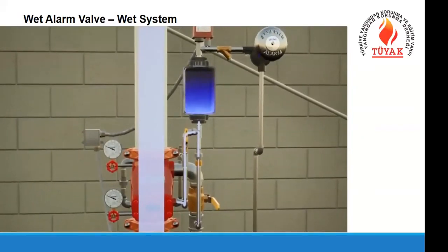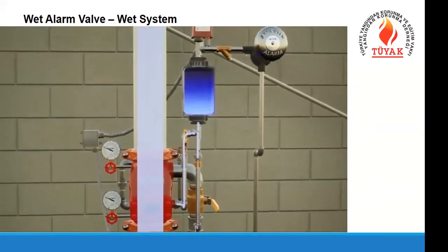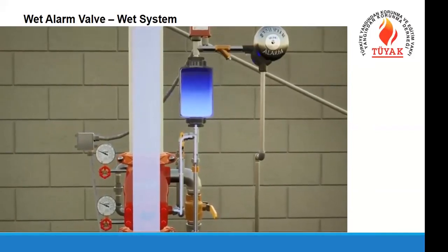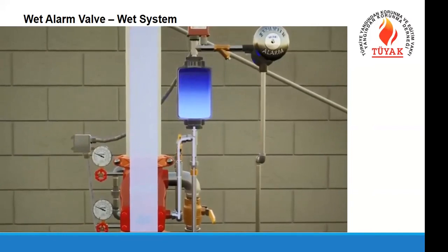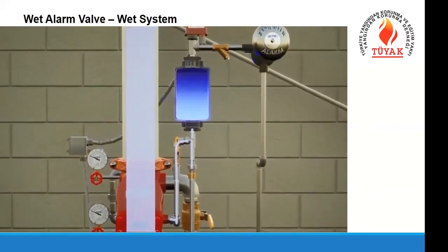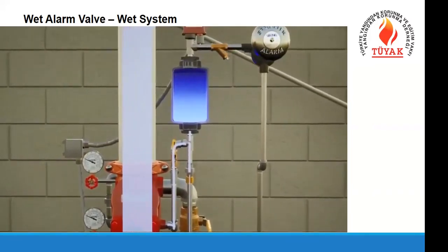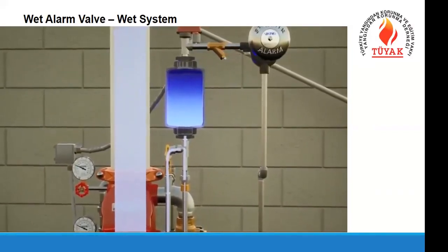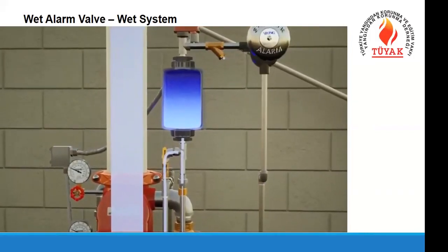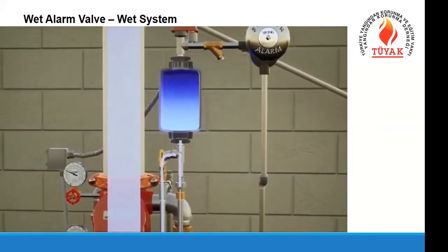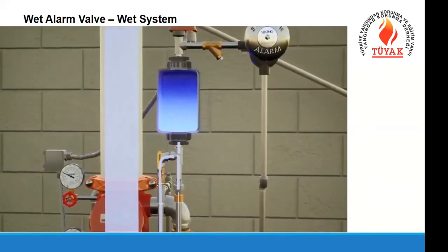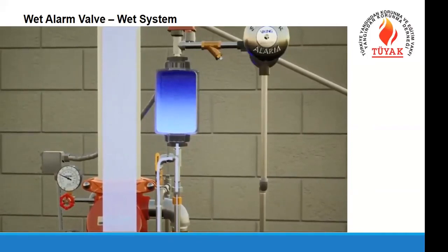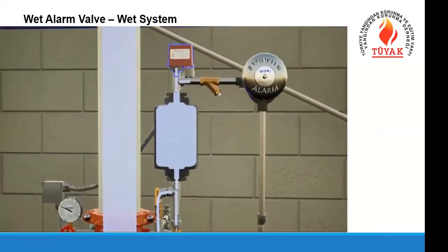The retard chamber is a device that prevents false trips by containing up to a gallon of water flow prior to creating an alarm. Inadvertent water flow will only fill a portion of the retard chamber's capacity. The alarm line is equipped with a 1/8 restricted orifice that allows the retard chamber to drain externally and reduces false alarms. During a fire, a consistent flow of water enters the alarm trim and fills the retard chamber faster than the restriction can drain, and the water flow continues through to the alarm devices.